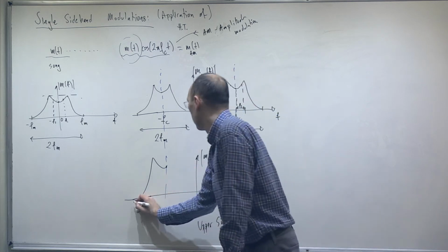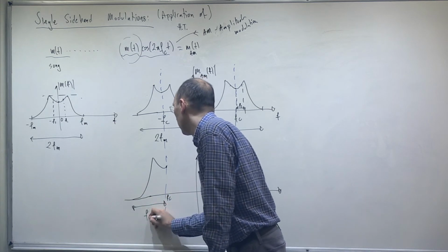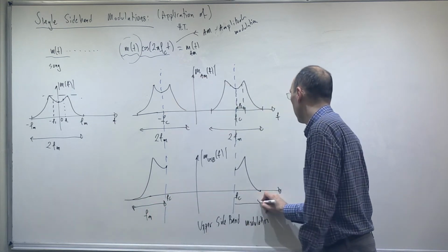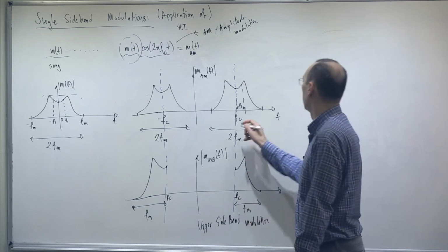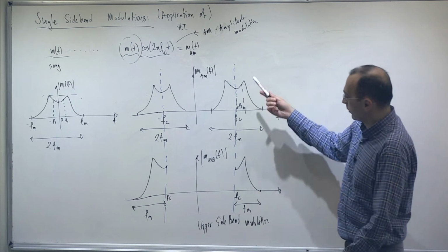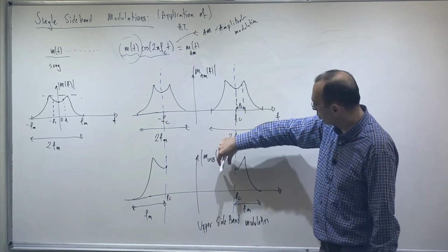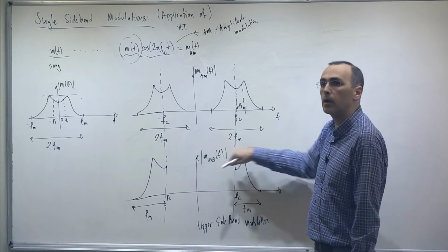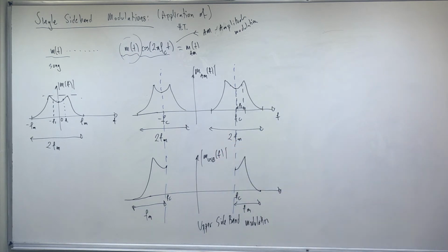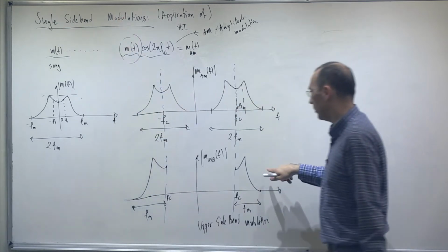Okay. So again, this would be fc, and this would be the maximum frequency, fm, so it's the same thing. So if I can transmit this through this radio channel, then there is some occupancy over here. Some other radio channel can also use this part, clearly, if I can manage to do this. So this is called, as you can see, single sideband modulation scheme number 1.